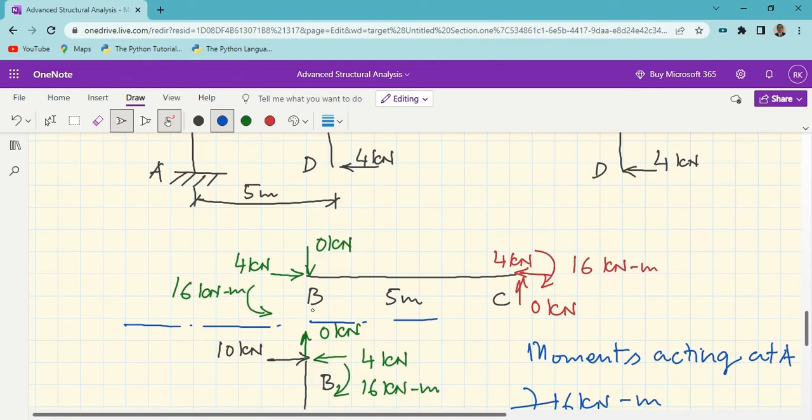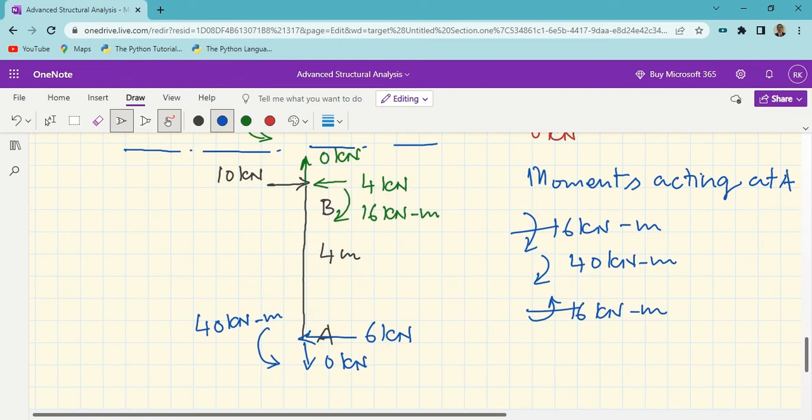And my friends, it is very clear, once we draw the correct free body diagram, it is very easy to plot the bending moment diagrams. It is very easy to analyze the structure. It is very simple to write the moment equations for the portions CD, BC and AB, which is required in our flexibility analysis as well as strain energy analysis. In our next video, we will discuss flexibility analysis, and in that case, invariably, we need to draw correct free body diagrams.